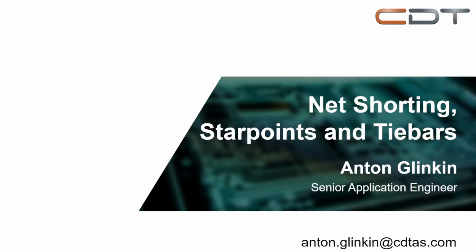And today I want to talk about different techniques that exist in Expedition and Xpedition Professional as well to create net shorting. Net shorting is not really commonly used, but it's quite often used when we're talking about ground union, about ref stuff. It can be very tricky sometimes since SES and constraint management in Expedition very often prevent you from doing this, and it may be not very intuitive.